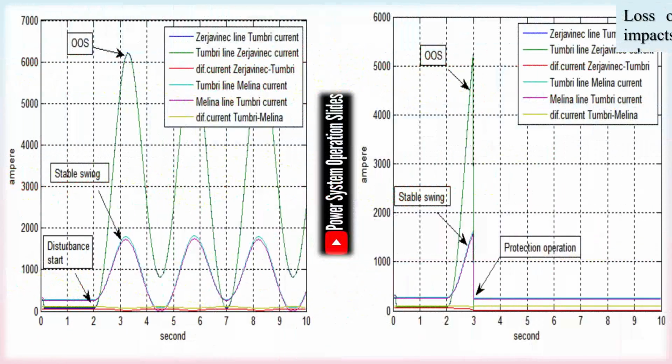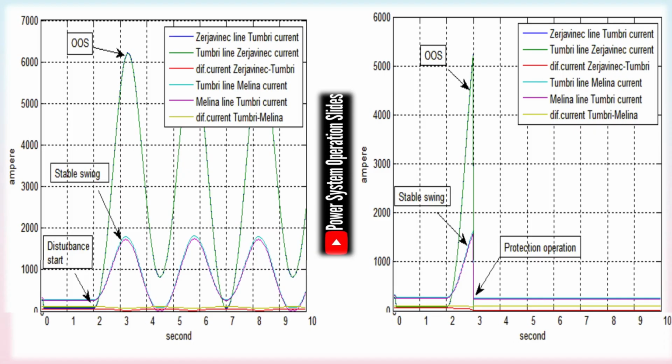Loss of synchronism, or an out-of-step condition, impacts transmission line relays differently. Some relay systems like segregated line differential relays remain unresponsive during these events, while others such as overcurrent, directional overcurrent, and distance relays may react to changes in voltage, current, and phase angle relationships. In some cases, these relays might even trigger during stable power swings from which the system can ultimately recover.